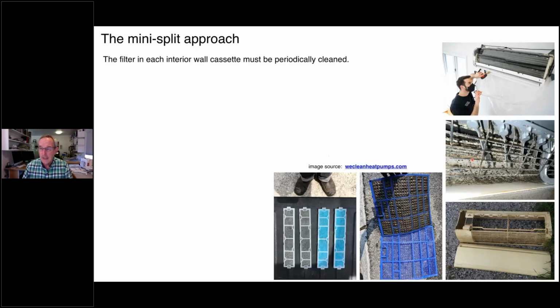So what we're looking at here in this upper right corner is a fellow, and he's got a small electrically powered pressure washer. And you'll see that clear bag that's been installed under the unit. So he's basically spraying a mixture of some type of a disinfecting detergent and water up into that unit. And he's catching that water as it drains out along with the remnants of that film that was in there. So the coil and the interior cabinets really need to be washed, and the recommendation is once per year.